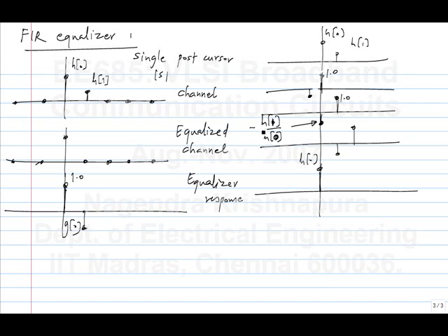It also makes sense that it is H1 by H0, because if there is no ISI, if H1 is 0, it should go to 0 also. So the next one will be 0. And what is the next one going to be? H0. It is assumed that H1 is less than H0, because my cursor is where the peak occurs in the response. When I send a pulse through the channel, I get something, and I sample at the peak. Somehow the clock is adjusted so that it samples at the peak, that is H0, and everything else is clearly less than the peak, so that's H1.